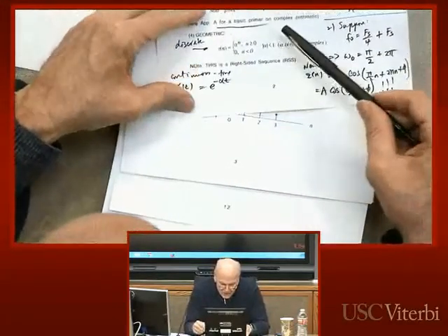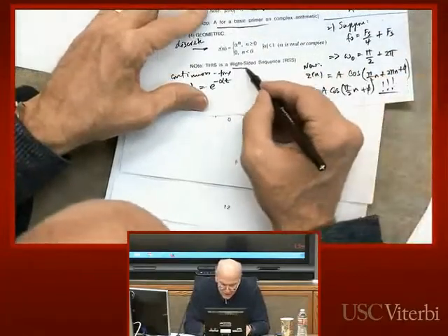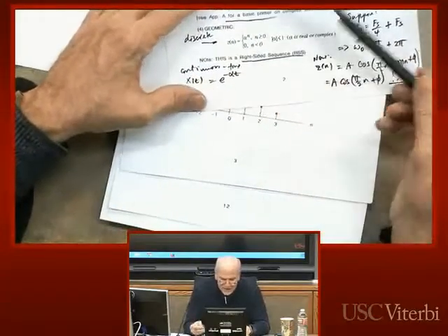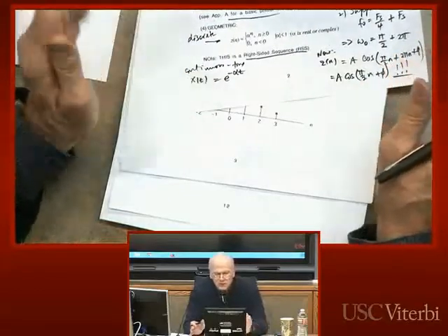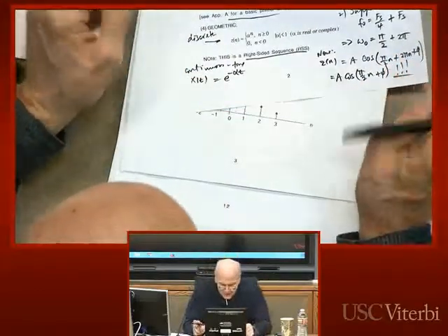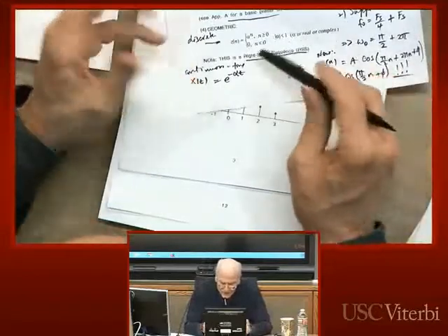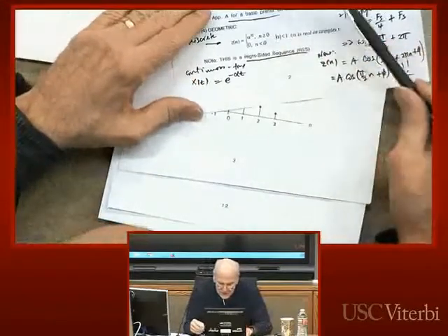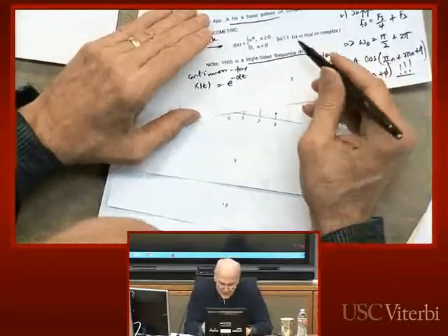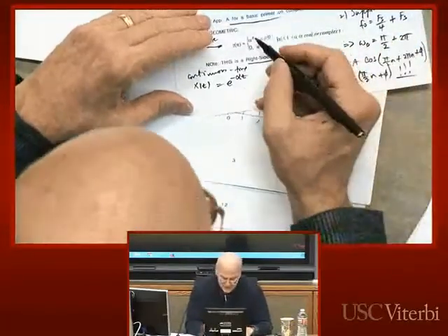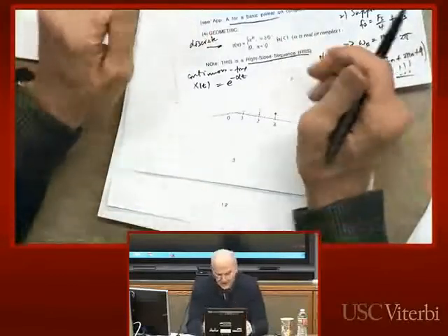So here would be, for example, what is called a right-sided sequence. Right-sided sequences are simply sequences which are 0 for n less than some n naught value. Here I've chosen one where n naught is 0. So this is a right-sided or one-sided geometric sequence, and it looks just like the continuous time. Well, I shouldn't say exactly like.